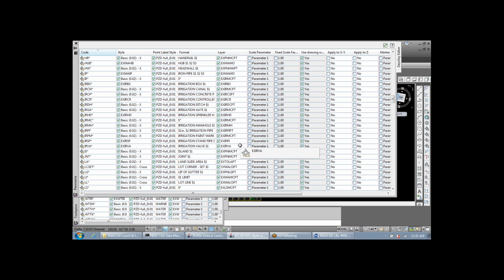This is something I'm open to change, quite frankly. I would not have set it up this way. If you had asked me to set up a point description key, I would not have chosen to set it up this way, so I'm inheriting this more or less. That doesn't mean we can't change it though. I think it's a little too complex personally, in terms of having the label style and all these layers. You guys have about 400 layers for points because you need the PT and the regular layer. So you're looking at 400 layers just to handle your points. So I'm open to hearing suggestions on this and what you guys want.